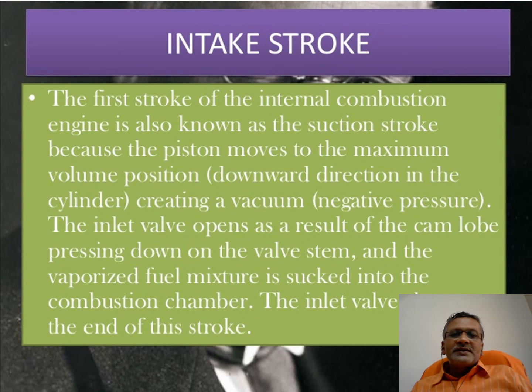Intake stroke, this is. The first stroke of the internal combustion engine is also known as the suction stroke because the piston moves to the maximum volume position, in the downward direction in the cylinder, creating a vacuum, negative pressure. The inlet valve opens as a result of the cam lobe pressing down on the valve stem, and the vaporized fuel mixture is sucked into the combustion chamber. The inlet valve closes at the end of the stroke.